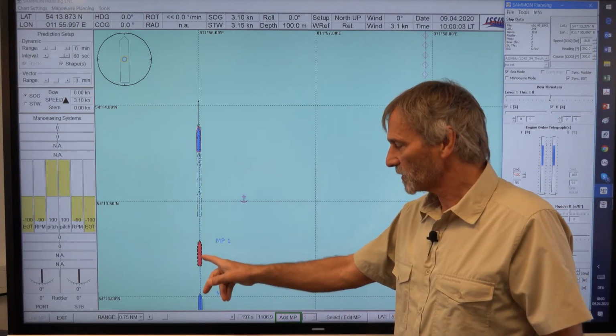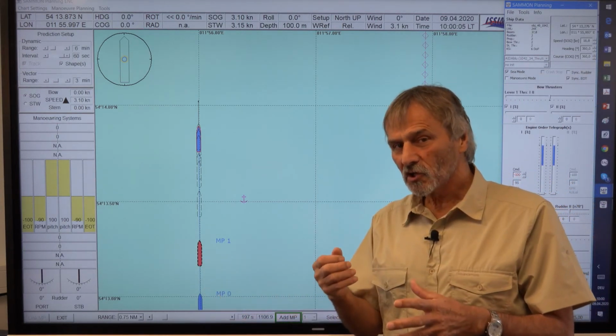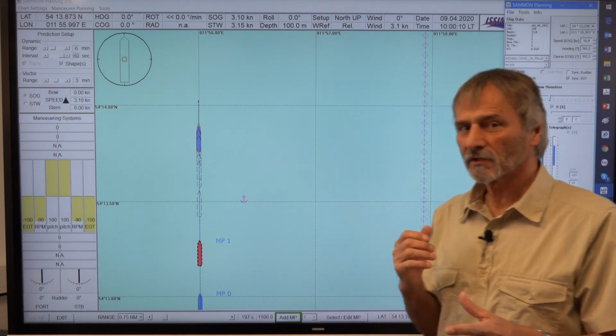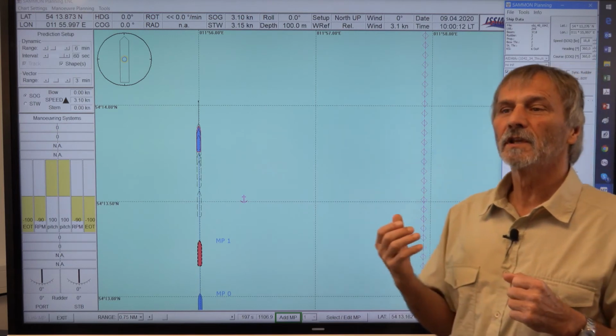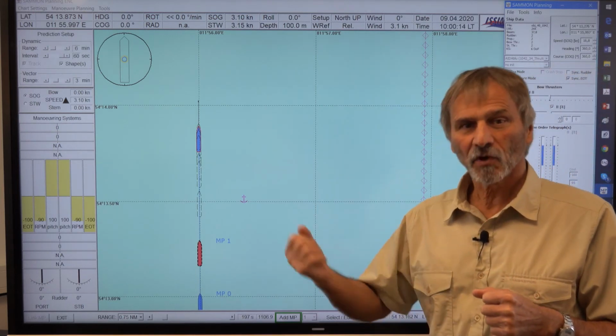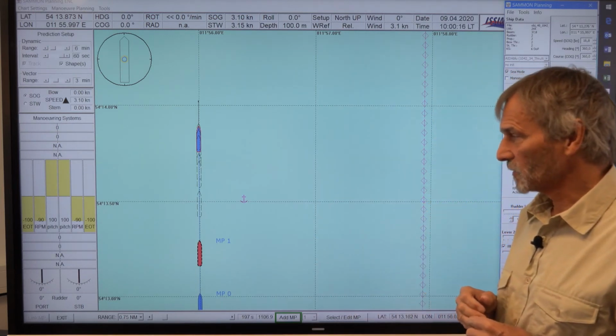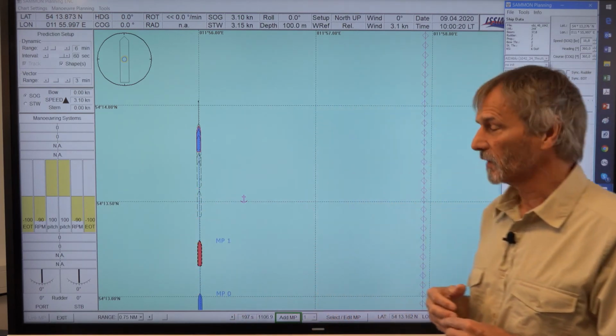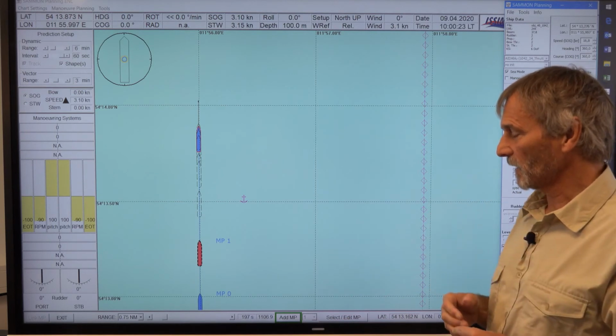When we go along this side, we already adjust one engine to astern. So it's slightly going astern, then you avoid the reversing time of the engine which you need. So we have seen that it takes a while until the propellers are working in a stern direction.